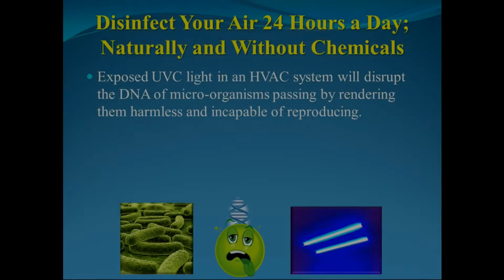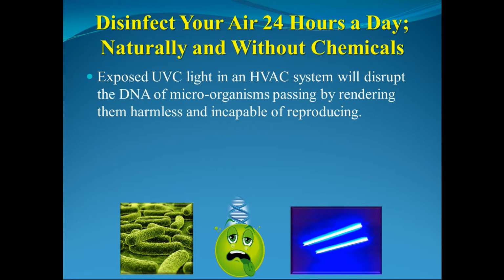Well, when we expose UVC light in an HVAC system, that UVC energy is going to disrupt the DNA of microorganisms that pass by it, and it's going to render those things harmless and incapable of reproducing. Does that mean it kills them all? It doesn't necessarily mean it kills them, but it's sterilizing them. What it's doing is breaking down their cellular structure.